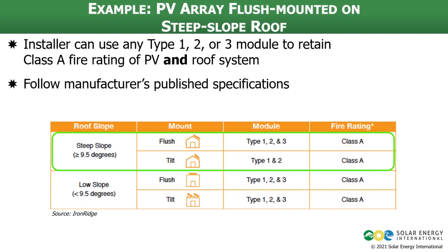Of course, with any of this, you have to follow the manufacturer's specifications and published manuals. That is part of the UL listing. The National Electrical Code makes you follow those listing instructions. So be sure to understand what your manufacturers require. And if you don't understand it, ask them to help you out, because all the racking manufacturers will help you out with this stuff. It's not like you're piecing together all this module type and PV racking type.